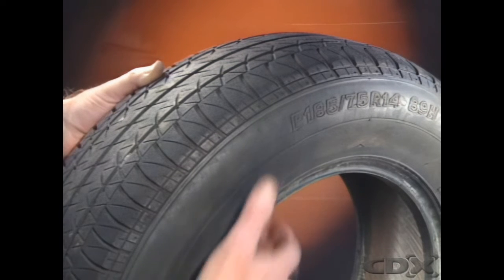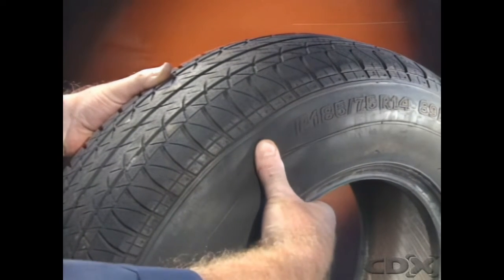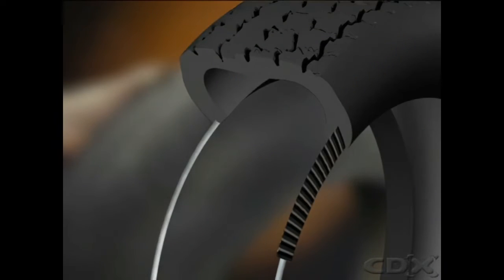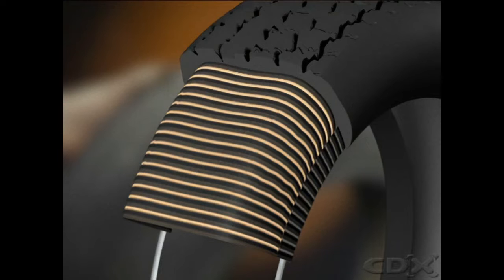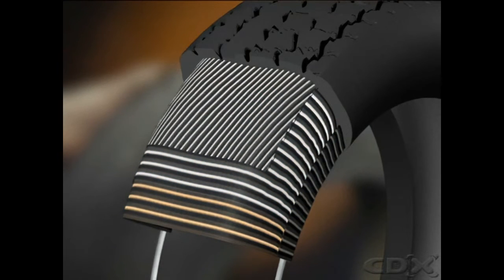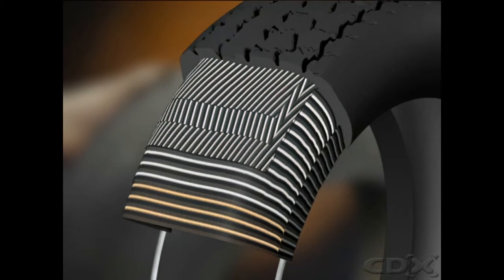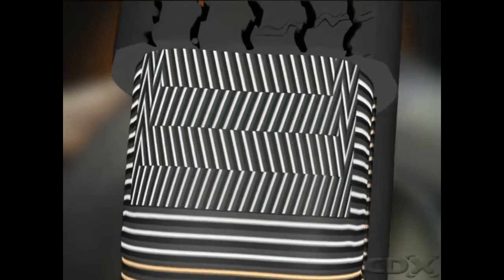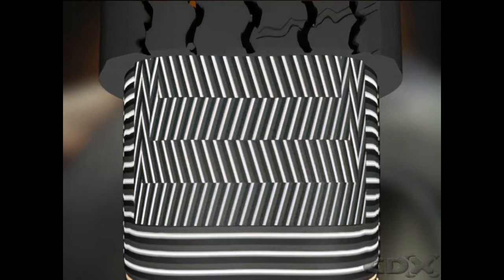Radial ply tyres have much more flexible sidewalls due to their construction. They use two or more layers of casing plies, with the cord loops running radially from bead to bead. The sidewalls are more flexible because the casing cords do not cross over each other. However, a belt of two or more bracing layers must be placed under the tread. The cords of the bracing layers may be of fabric or of steel, and are placed at 12 to 15 degrees to the circumference line. This forms triangles where the belt cords cross over the radial cords.